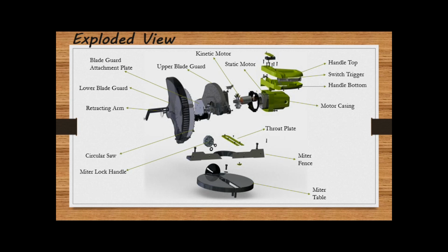I learned today that there is something called a runoff, and this runoff causes the blade to move away from the line that you want to cut. The one way that I think we could improve this design, and Marcus and I discussed this briefly, is to place a spring on the opposite side of the blade so that when the runoff pushes the blade away from your cut, the spring on the opposite side would push it back towards your cut, preventing that issue.